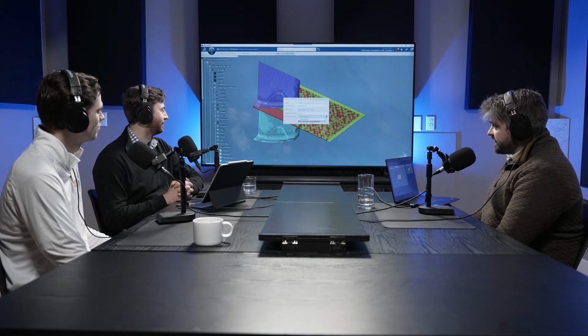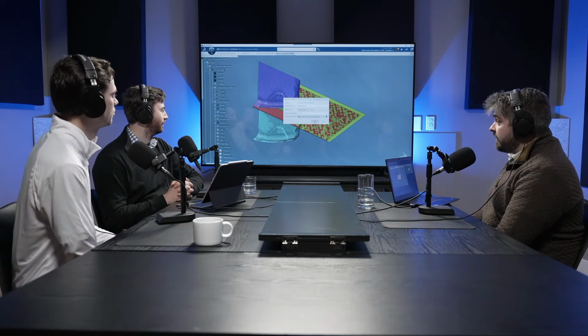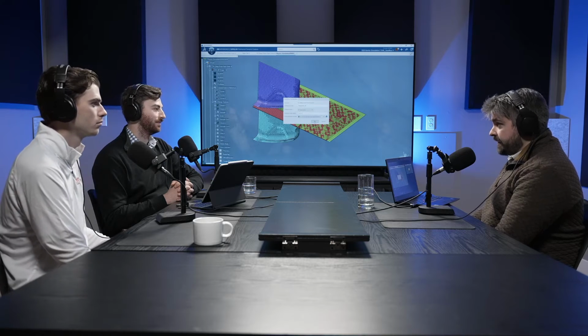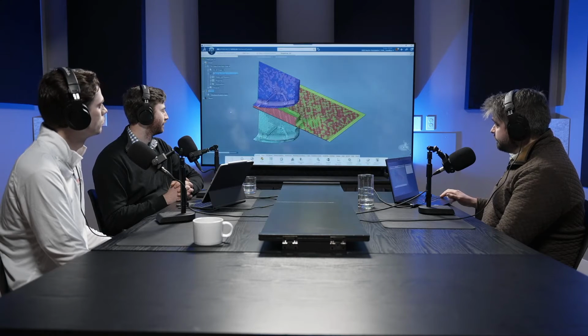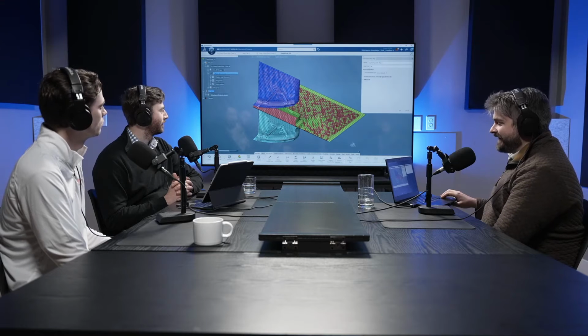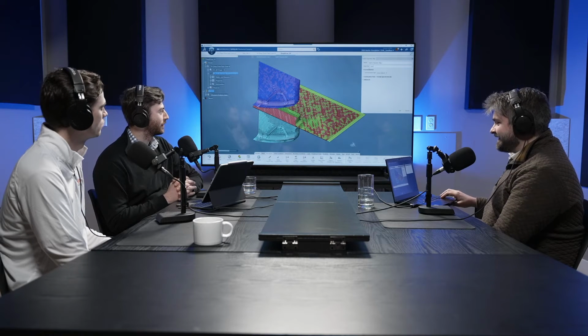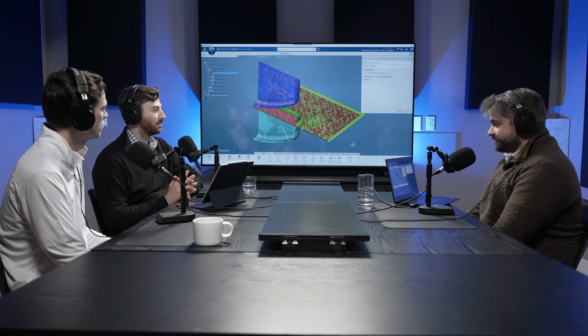I can pick what type of study I want to do here. And because this is going to be a structural simulation, that is what we do. I can also do thermal, things like that, but it's not really applicable in this particular application. Once I go through, I can go ahead and run it and I can get my results accordingly. Setting up the step itself, we're seeing explicit dynamic here, and that's that big differentiator in terms of complexity.